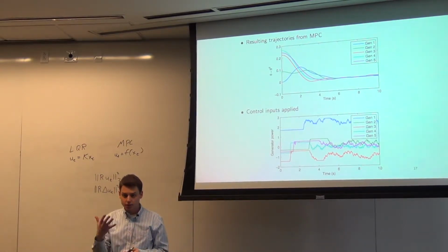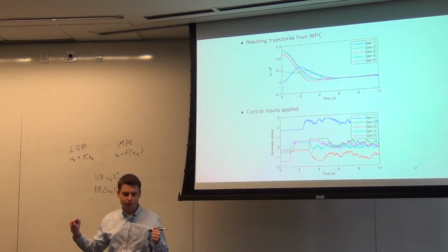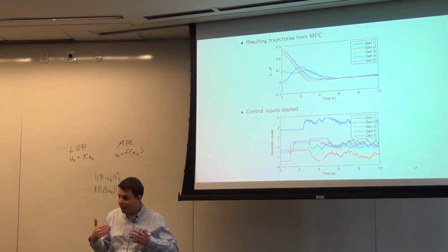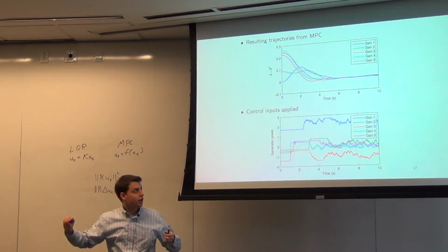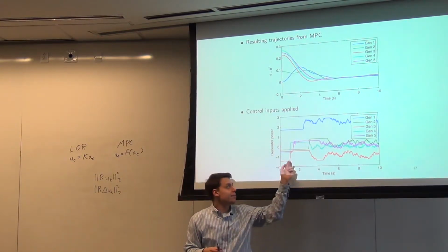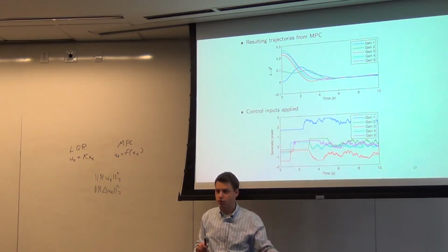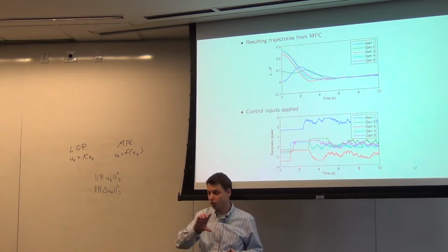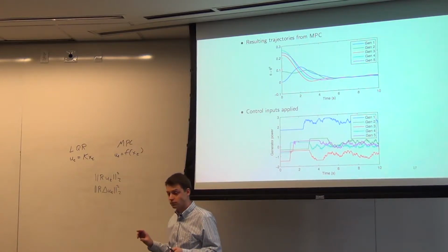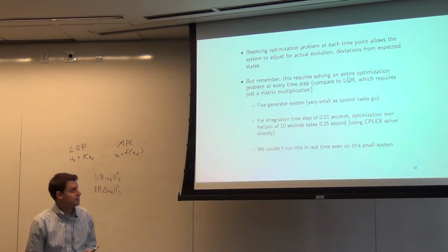We have some deviation from the smooth controls you would plan from just controls optimization. You have to, because there's some noise that creates different variations than you would expect. But with MPC, you have absolute bounds on how far you ever deviate from the desired control. Not just the penalty you pay as you do with LQR, but actual hard constraints here. So that's the basic idea of MPC. It's a really simple algorithm. And importantly, it's not optimal.